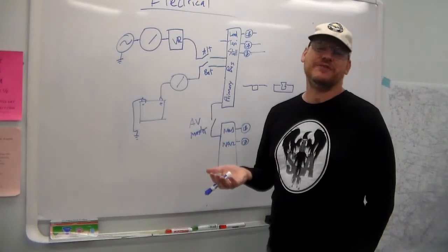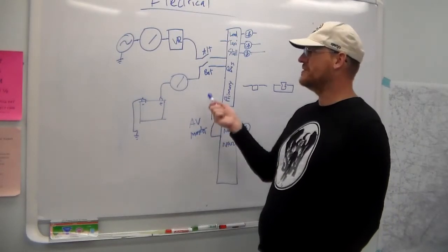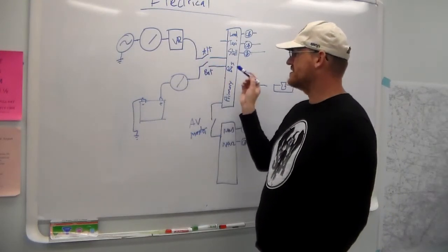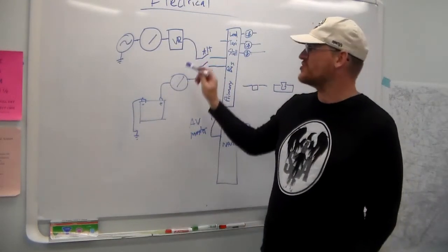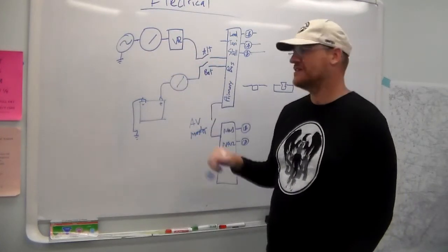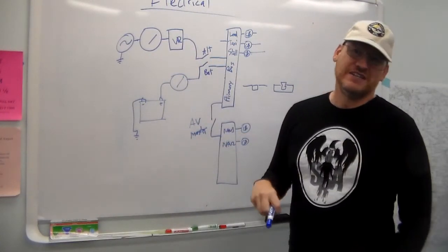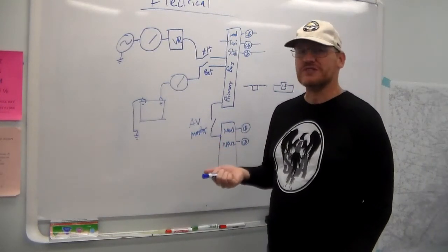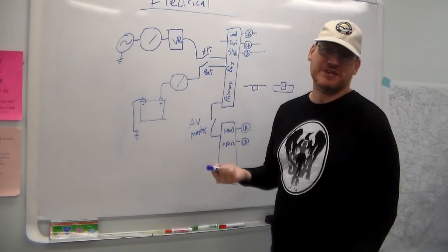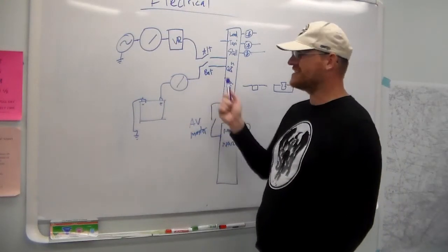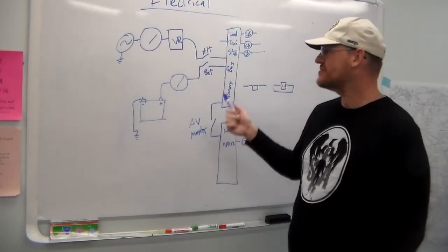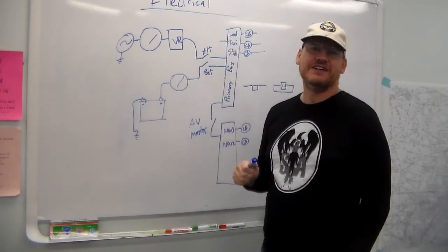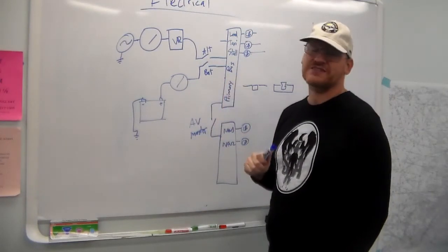We talked about that before, and we said that normally you want to have both ignitions on. Well, what if there's a problem? Maybe there's a problem with the alternator. Something's failed in a way that it's sucking power from the battery. Maybe there's a short somewhere in this system. So you might want to turn off the alternator side. What if your battery suddenly went bad? You know, they can get things like internal shorts, and they can fail suddenly. It happens sometimes. And you might want to isolate it. So those are the only conditions where you'd want to turn off one side of your master.